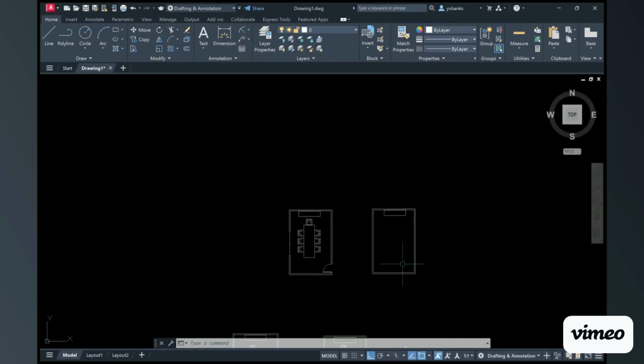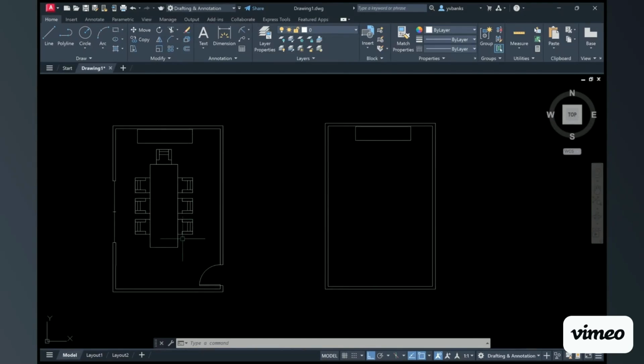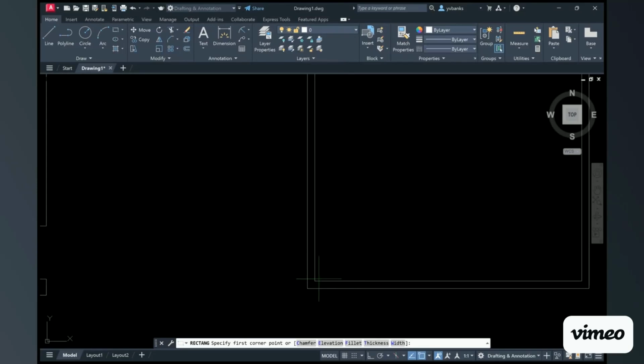We're going to repeat this same kind of step for this conference table. The conference table has a distance of 5 feet off of the left interior wall, and 6 feet from the bottom. So again, I can use my polar tracking to create that marker. Polar tracking here is going to go up the wall 6 feet.